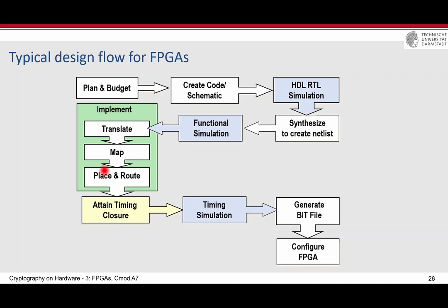And then after that, when you have implemented this, means that you just said, okay, exactly for this FPGA that I want, I know that, okay, this block RAM goes here with this configuration, this switch box should be configured like this, lookup table should be configured like this, and you do completely everything is now done, and you are sure that you can build your design or put your design on that FPGA.